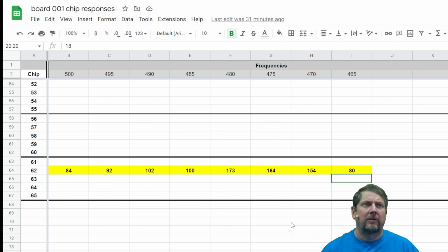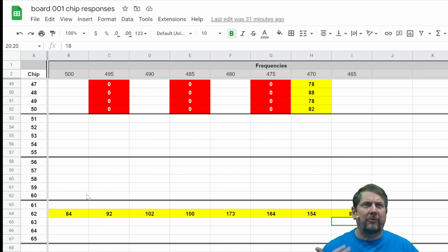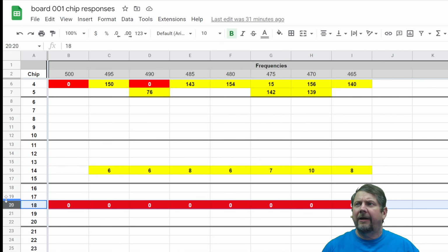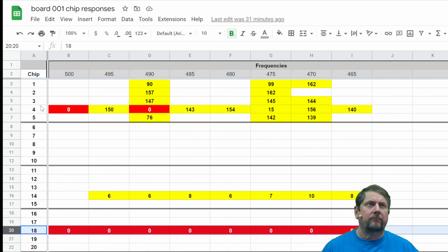So this first round, I'm going to replace 62, 44, 18, 14 and 4, because those were chips that were always bad in the tuning. I'll take those chips out, put the board back in the Hiveon loaded miner, and run it again and see what happens. Hopefully, after I straighten out these weak chips, I can put it back into my Vanish loaded miner and won't have any temperature sense problems.